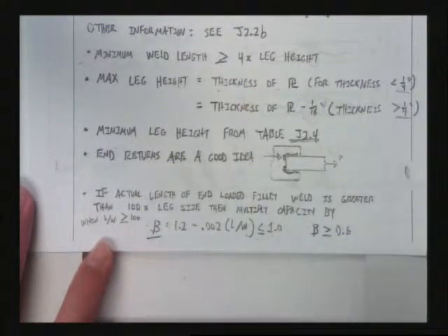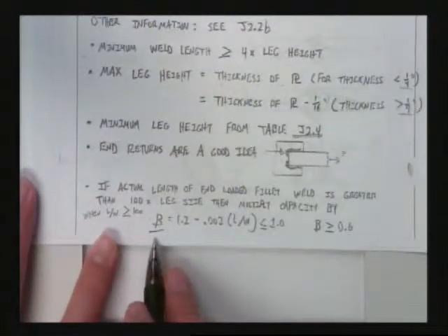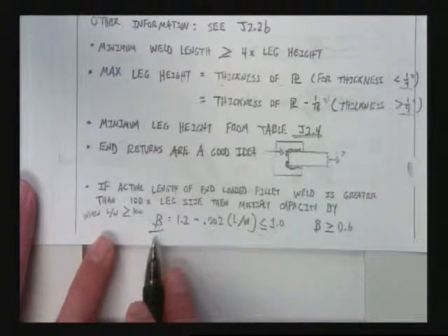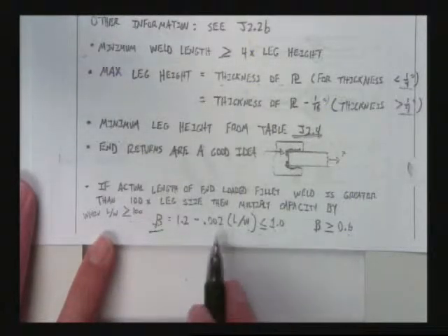In very, very long welds, because the welds are so brittle, that may not occur. Structural resiliency may not be able to occur. We may not be able to get the strain and ductility that we need out of our connection. So because of that, we put another safety factor on top of it.